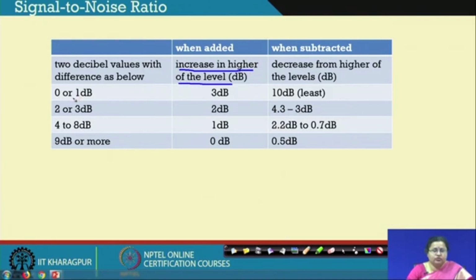So, if you have 2 sound sources producing almost the same sound, say 70 decibel, then the overall sound level in the space is increased by only 3 dB. So, 70 will be increased by 3 dB, that will be 73 dB if 2 sound sources of 70 dB are working. But we are not concerned with this part, because we are going to calculate the difference. This has been already explained and discussed. I have given this chart comprehensively so that you can both add and subtract.